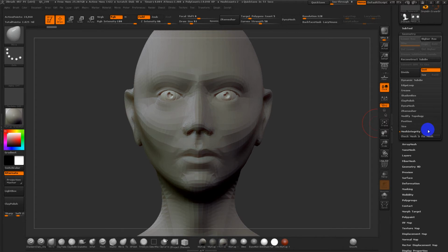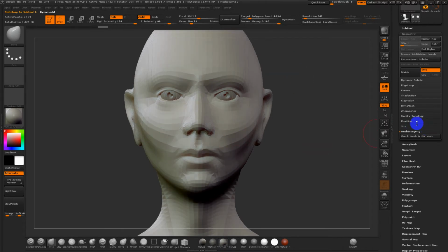So what can happen, particularly with mesh that you need for blend shapes? Blend shapes are very sensitive to the vertex naming and ordering or numbering, as well as the mesh layout. So if there's any little bugs and you fix those bugs, the problem is you may destroy your blend shapes afterwards, which means you have to redo all the blend shapes. So you want to try to clean the mesh and make sure it is as production ready as possible.